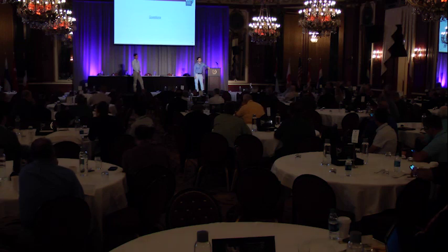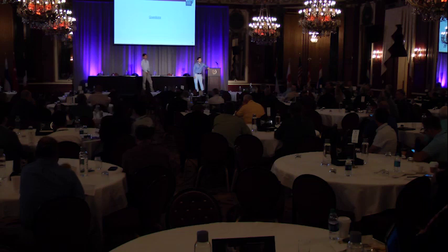So when the beams were cut, he didn't request shoring in the correct location. Luckily, they lost some roof bays, but it happened after hours. It was a ballasted roof, so a whole section of roof collapsed.